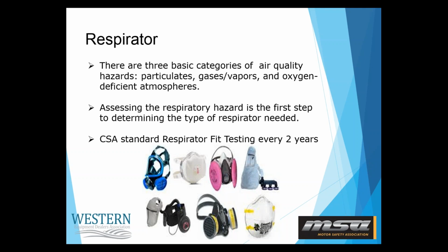Safety data sheets will also indicate the requirement for respirators, but a lot of times they may not spell out what type of respirator to use. So that's when we have that good relationship with our supplier, where we call them and determine what our hazards are, and they make the recommendation for the correct type of respirator to use.